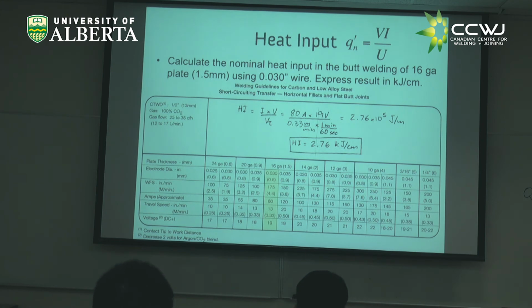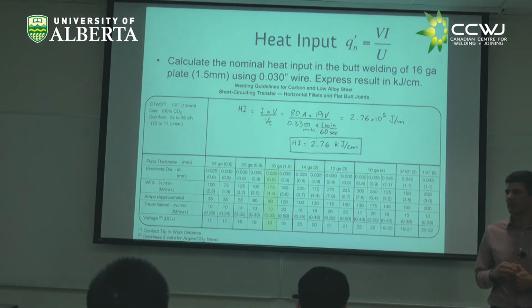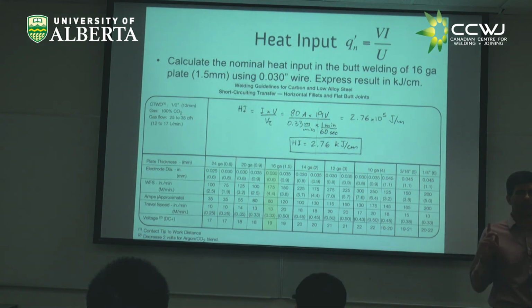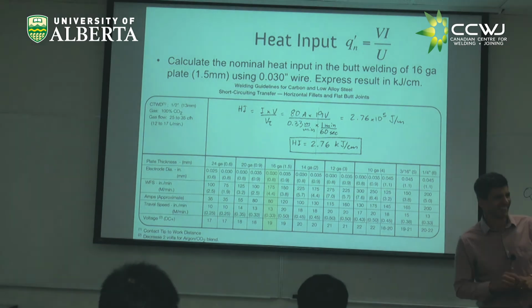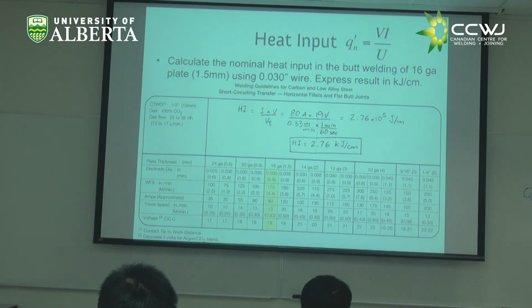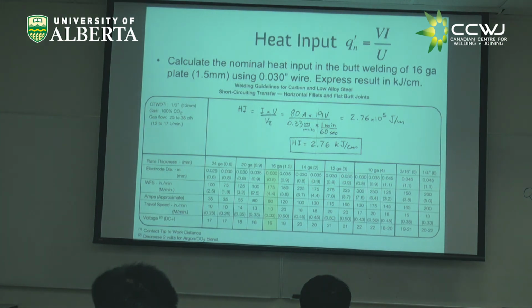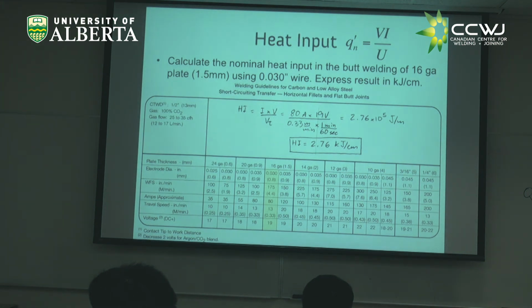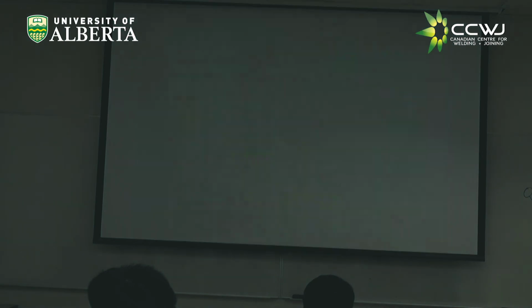So I have 15 minutes now. For going quickly over welding symbols, do you have any questions about naming, other than, do we really need to learn all this? And the answer is yes. This heat input matters so much, and it goes into formulas, and the t8/5, the time to cool from 800 to 500, also goes into formulas.